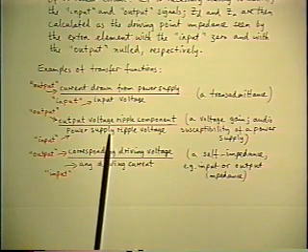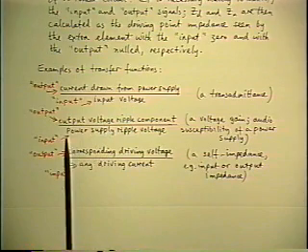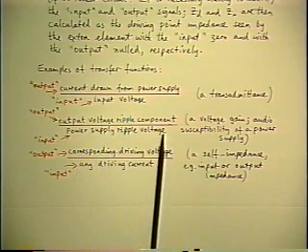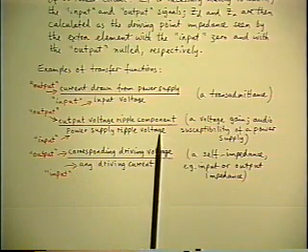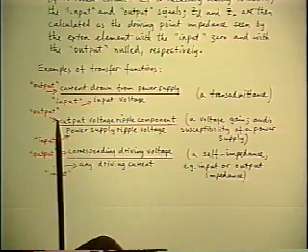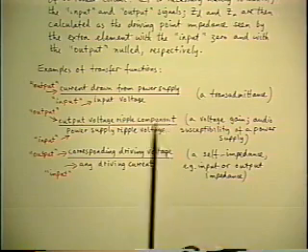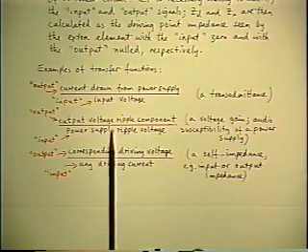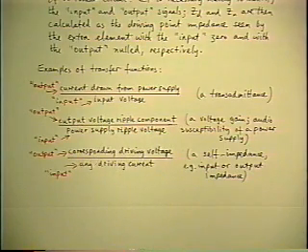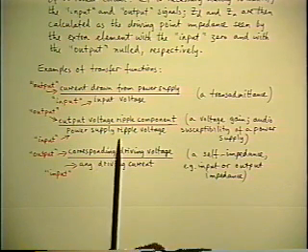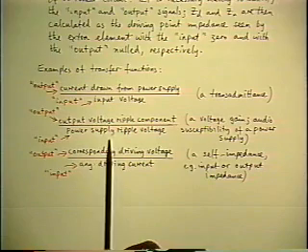So there is another transfer function that says, considering the power supply ripple voltage as another independent input, the transfer function that says how much output voltage ripple you're going to get resulting from that is another transfer function that has to meet a specification. That's a voltage over a voltage again, so in a sense it's a voltage gain.